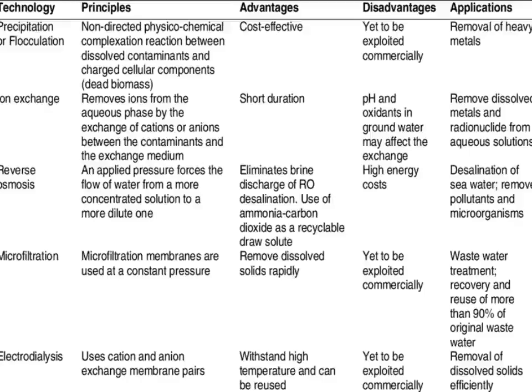Another technique is the removal of mercury from chlor-alkali plant effluents. Mercury thrown out from chlor-alkali plants gets removed and recovered by mercury selective ion exchange resin. Then removal of phenolics. Phenolics in wastewater produced from industries such as pulp and paper mills, carbonization plants, petroleum refineries, tanning industries, tannery industries, and resin manufacturing units are removed by the use of polymeric adsorbents.